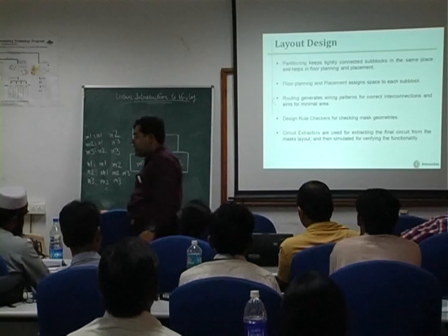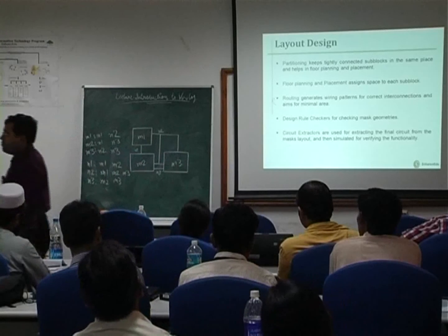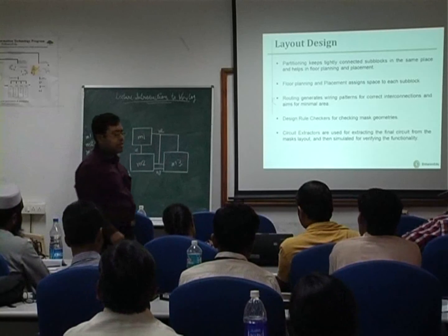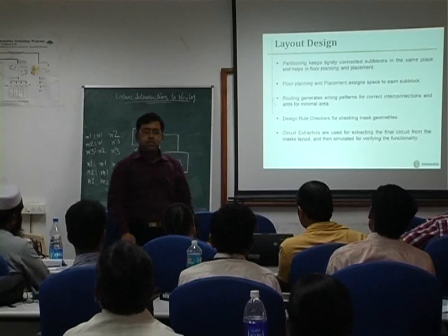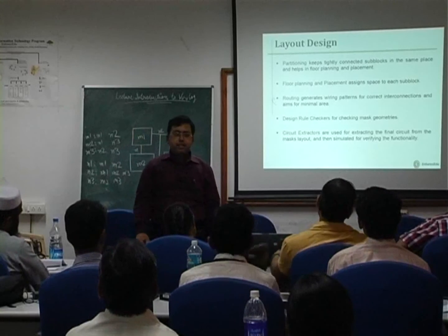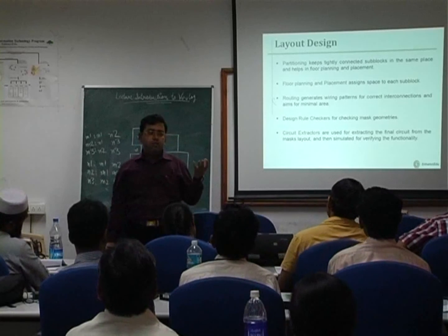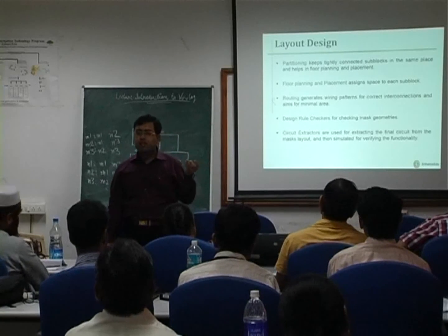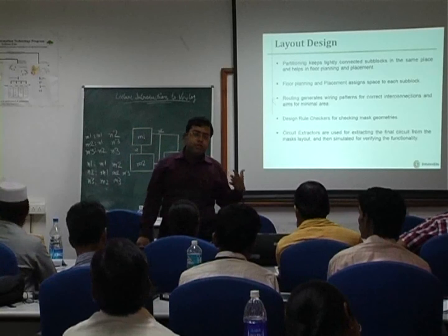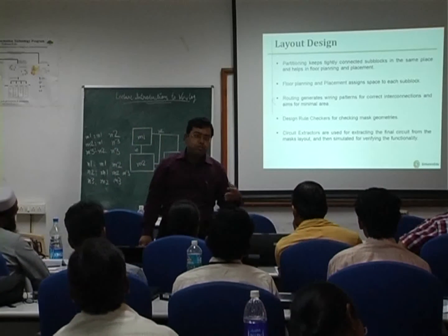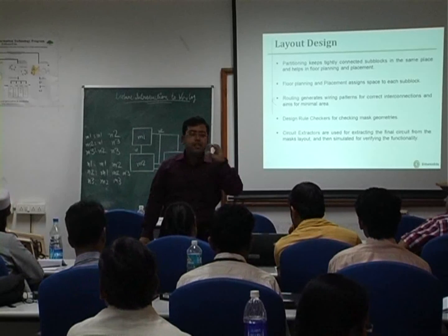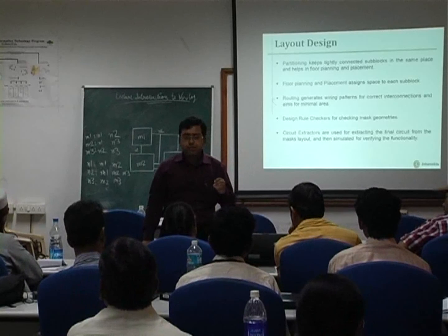So this layout design process is a multi-step process which starts with partitioning the circuit into certain sub-circuits and analyzing each sub-circuit, which is what we mean by circuit partitioning, so that the circuit analysis and design process becomes a problem of manageable size. And then we come to finding out in what part of the chip we will place the individual components. That is basically the floor planning phase.